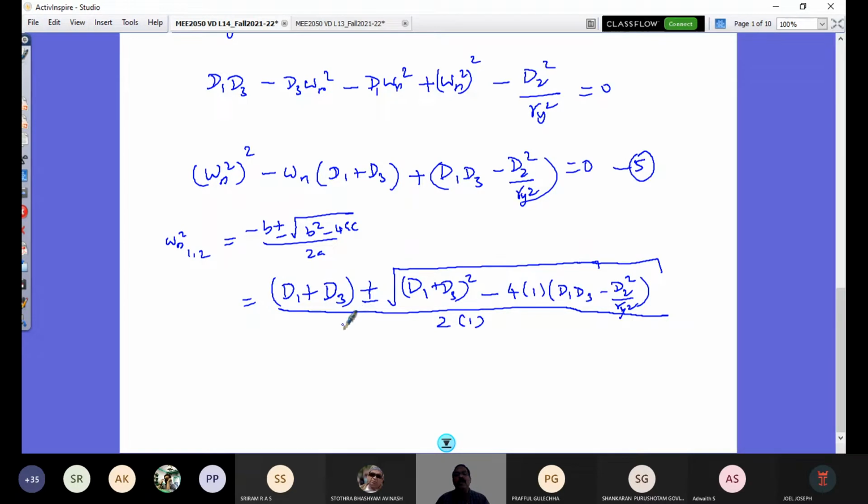If you see the frequency of the three rigid body modes of your vehicle body, bounce, pitch, and then roll. In this model, we do not consider roll. If you have to consider roll, then it is a 3D model, a three-dimensional model. But for in-plane model simplicity, we have neglected roll at this point of time. And if you look at the frequency values, they would be in this order. The smallest of the three would be referring to bounce, and then pitch, and then roll. That's typical of values in a passenger car segment. Unless the front suspension and rear suspension are coupled and so on, that is special vehicles that we will not see. Generally, the order of frequencies, the lowest is referring to bounce, and then pitch, and then roll. So remember that. And now here, this is what is your omega n 1 comma 2 square.